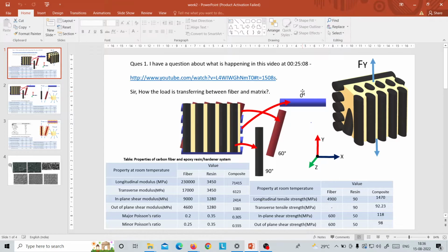So here you need to decide whether you want a composite to have low weight, or whether high weight is fine with you. If high weight is fine with you, you'll simply make a composite which comprises many layers of glass fiber, all at 200 rupees per kg, and you'll have a composite which will serve the purpose.